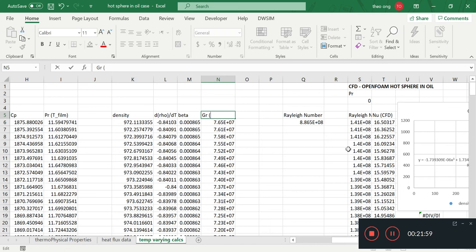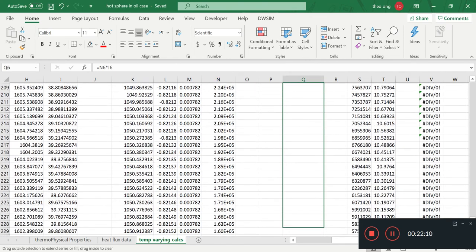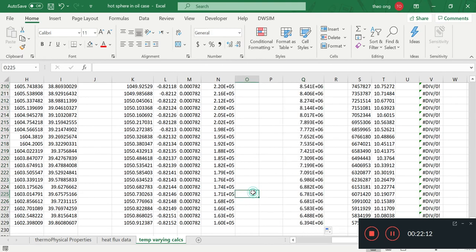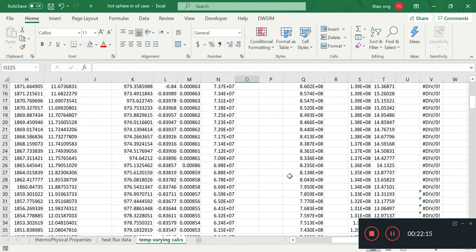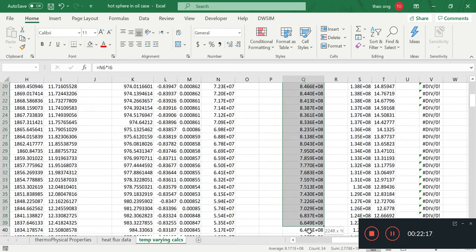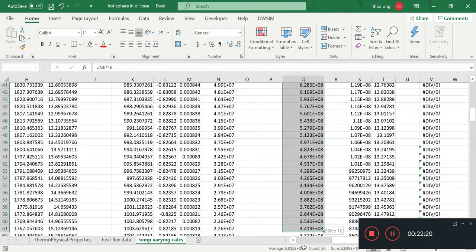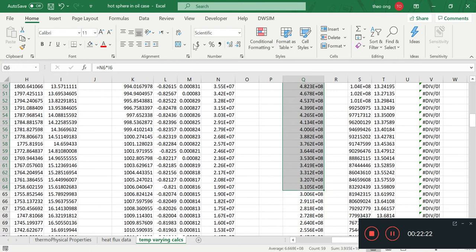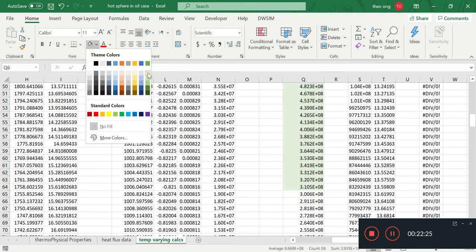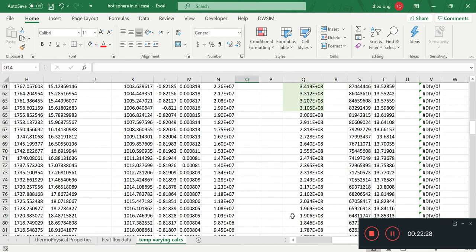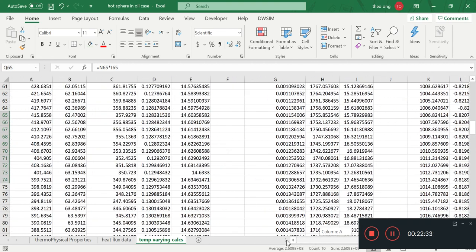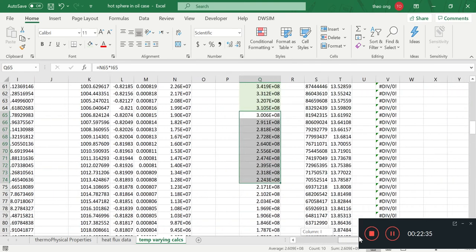The Grashof number is based on the film temperature. So the Rayleigh number is more than 3 times 10 to the 8, and there will initially be some turbulent phenomena. I'm keeping it general, because anything below a Rayleigh number of 3 times 10 to the 8 will not be turbulent anymore. It will be more of a laminar thing.